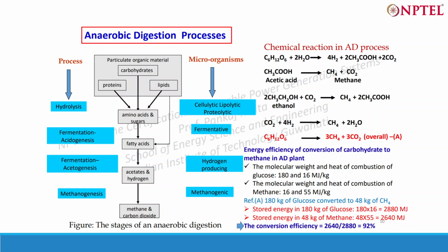and can be used as a fertilizer in the fields. So this is one of the advantages. And whatever biogas is produced, first the upgradation of that biogas occurs. Second, it is stored by compressing it in a cylinder. It is not like biogas is produced and then you just store it, because the rate of generation of biogas can vary depending on the microbial activity, but we need a constant flow of biogas with a specific pressure to burn it. That is why we store it in a vessel, and then that can be utilized for burning in the kitchen and other applications.